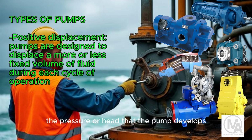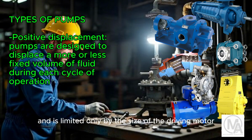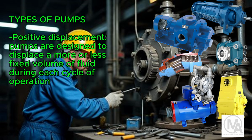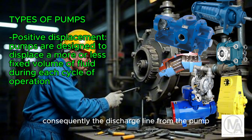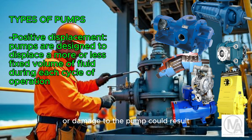The pressure, or head, that the pump develops depends upon the flow resistance of the system in which the pump is installed and is limited only by the size of the driving motor and the strength of the parts. Consequently, the discharge line from the pump should never be closed off without allowing for recycle around the pump, or damage to the pump could result.